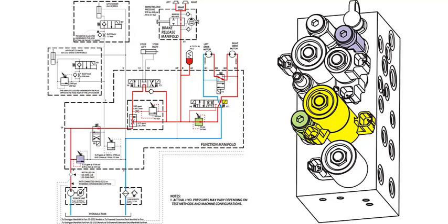With the drive valve in the center position, oil escapes from the spring-applied brakes allowing them to set, acting as a parking brake. This series drive circuit is an effective way to achieve a high drive speed and traction, but does not provide the torque necessary for larger models to climb inclines for loading and unloading. This is because of a low pressure differential across the first drive motor in the series. Generally speaking, if there is a low pressure drop across the motor, it is doing little work.